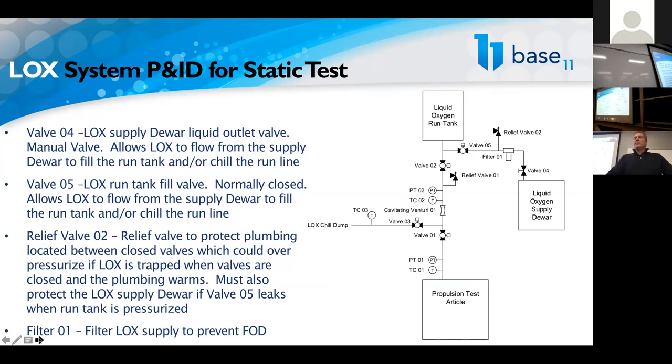My personal preference is to set things up to operate with propellants as remotely as possible. Now, there's a tremendous amount of manual operations done with liquid oxygen, right? All the valves on liquid oxygen dewars are manual valves. So liquid oxygen dewars are filled by using manual valves by the hundreds every day. So it's proper engineering to mitigate the hazards such that the risks are minimized.